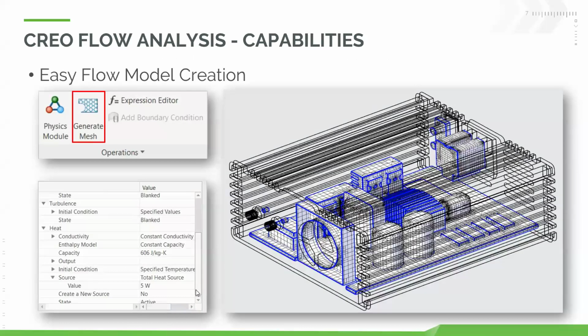You have the ability to tell Creo to generate the mesh in your analysis. You don't even have to define it yourself. You still have that ability to go in and define it more, maybe in areas that have more curves or more complex surfaces, or in areas where it's a much simpler, flat geometry, you don't need as much refinement. You can tell Creo, hey, expand our mesh here, and facilitate how the analysis itself is run much more efficiently than maybe running a full-on finer mesh or just a full coarse mesh as a beginning.